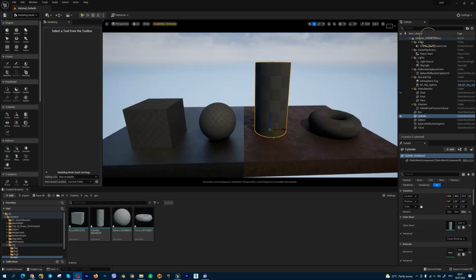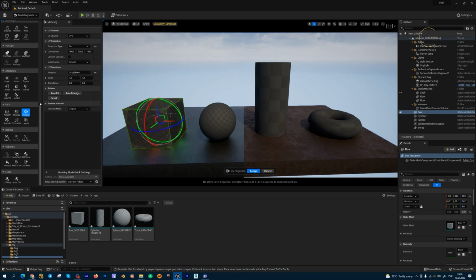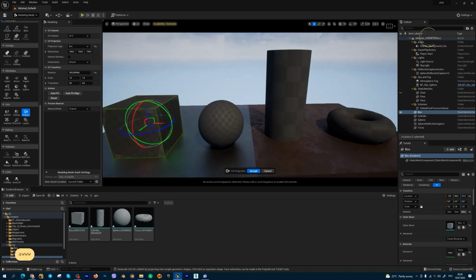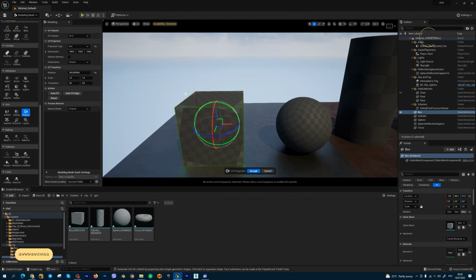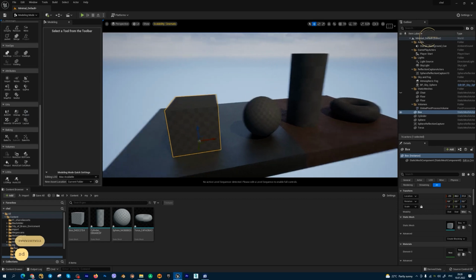Let's talk about UV coordinates and working with texture coordinates inside Unreal Engine 5. So we have the UVs tab, and we have some tools to work with texture coordinates inside Unreal Engine. The first tool I need to show you is project. This is a very simple, fast tool. It allows you to create different projection types such as box, cylinder, plane, and others. So let me put some materials on my object, and I can show you how it works.